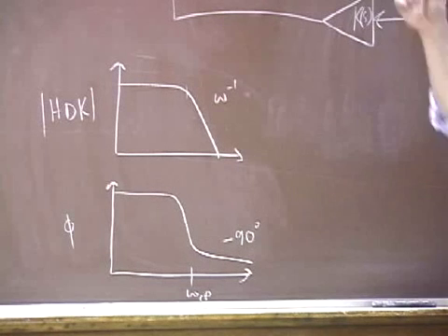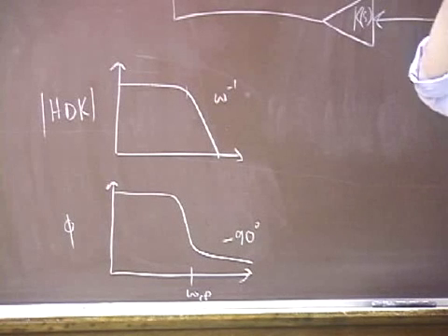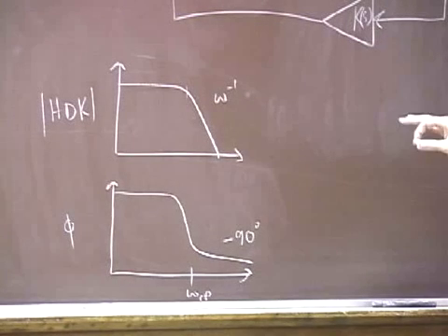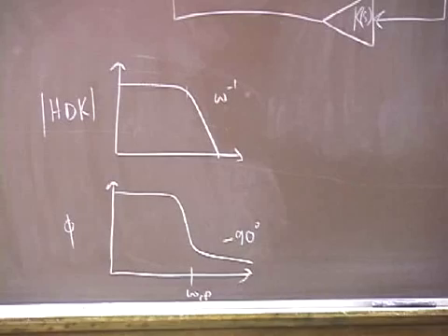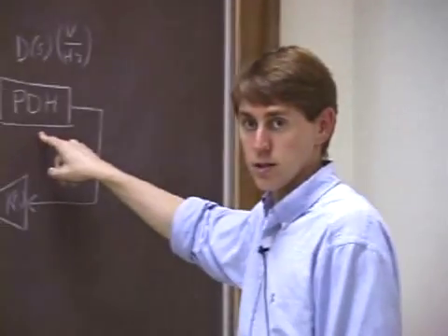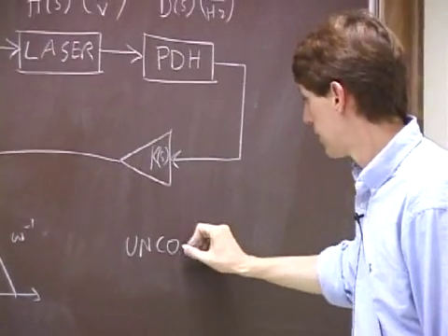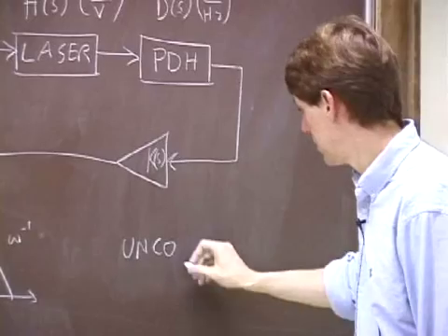And the boundary that we drew over there for the Nyquist diagrams never approaches the forbidden point, -1, at any time. So this system, admittedly a fairly artificial system, but one that only includes the cavity pole, is unconditionally stable all the time. You've assumed a perfect amplifier. Yes. K is constant. Yes.